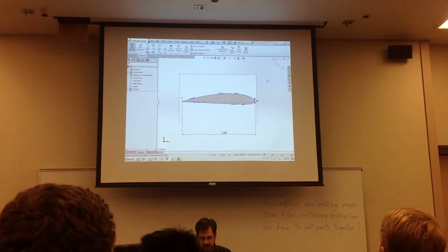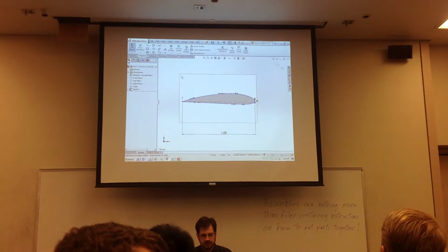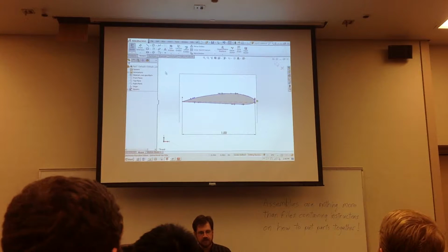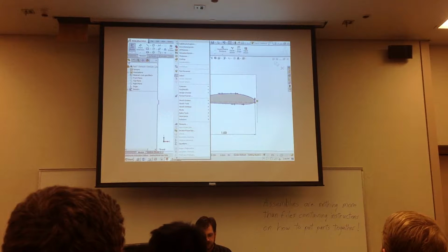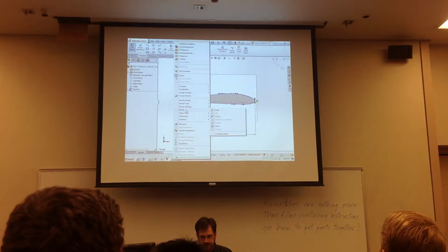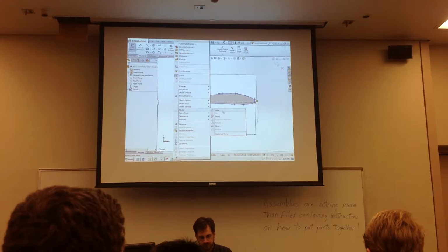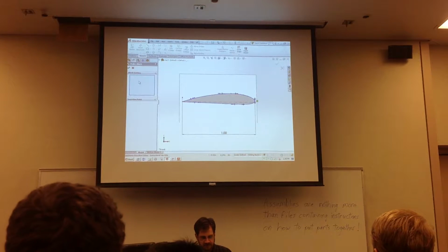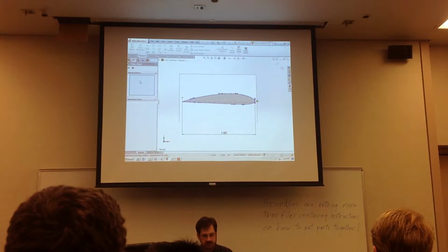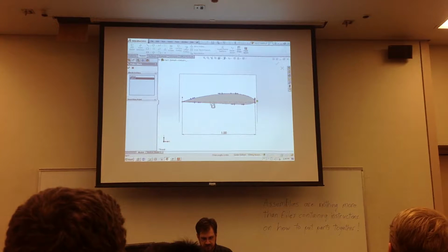So let's say I've played with that long enough, I'm happy with the shape, that I've matched the picture close enough. What I want to do now is save this shape into a sketch block. So this is another command sequence that you'll want to write down. To create a sketch block, you go to the Tools menu, go down to Blocks, and then click Make. Tools, Blocks, Make will bring up this selection box where you choose what you want to put into the sketch block. So I'm just going to click the 2 splines.